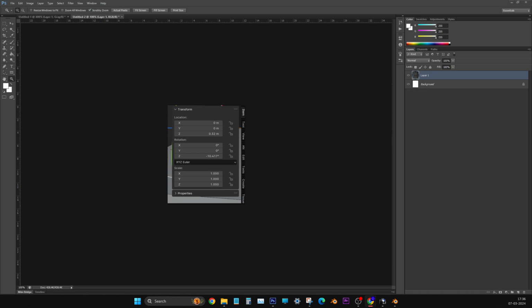Now go to move option. Yeah, just free move on that, keep it on the upper vertex, a little near. Yeah, it got snapped. Now you draw the rectangle in the same place, and that's why you press W. Yeah, very good. Now two vertices are selected, press M, distance, see, one vertex came, that's all, nothing else. You don't have to touch anything, because the old value is still there in the settings.